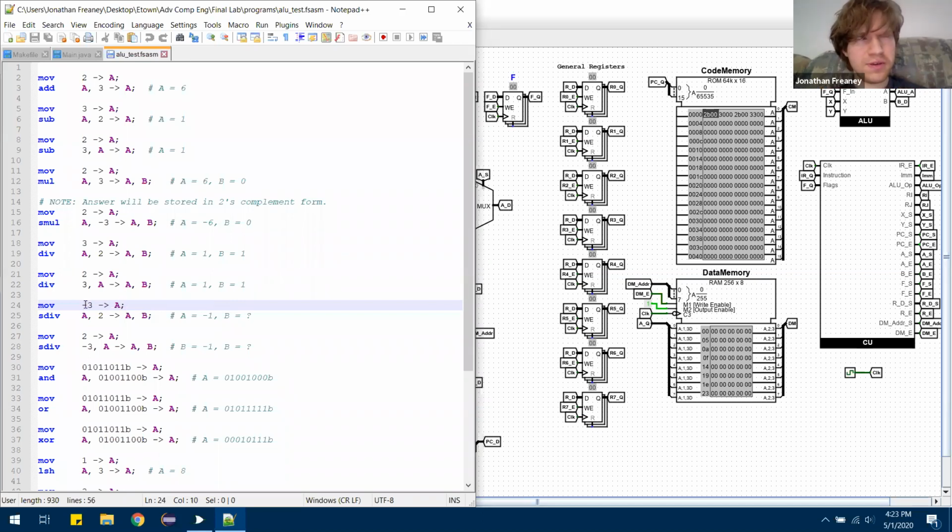Yeah, I also, in the assembly, you can make numbers negative, and all that actually does is, the way the assembler handles this notation is that every time it receives a negative sign followed immediately by an immediate value, it takes the immediate value during compile time and applies 2's complement to the binary form of it, which converts it into a negative form, right in the assembler. That's interesting. So this is a shortcut.